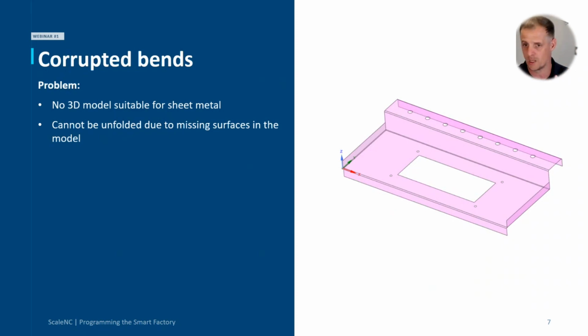Every time parts are converted from the native format into a STEP file or a common format, which is maybe shared by your customers, it could lead to parts not looking like they were made in the native CAD tool, and that could lead to them being corrupt after importing them into TruTops